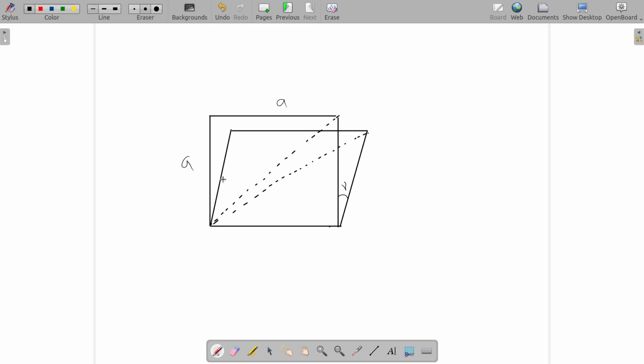So you have to actually assume that this angle is very close to 45 degrees, right? This is grossly exaggerated. So for a very small deformation, this length will be A gamma, because gamma is equal to this length divided by A. Now